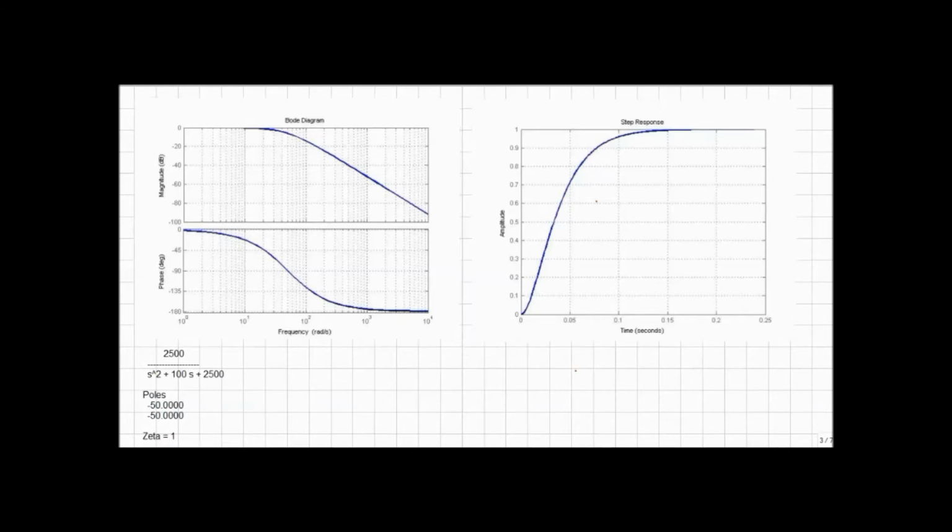And again, looking at our Bode diagram, I see 180 degrees of phase. I look at my magnitude and I see, golly, that's basically a straight line all the way up. So that tells me those poles have to be really close together. This should be 6 dB, and it looks like it's not far off.